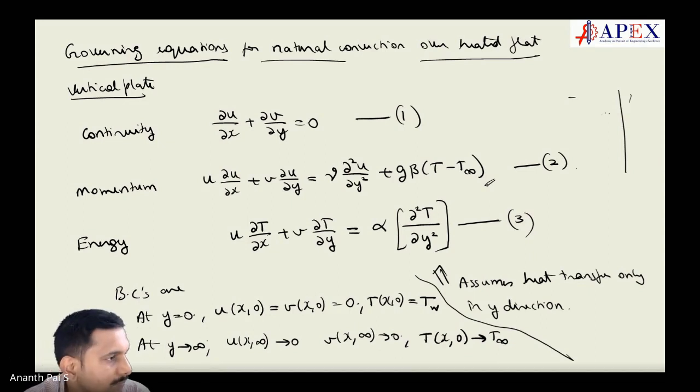pressure is not there. Since the pressure term is not there, what we generally do in CFD is first solve the energy equation. It's easiest to solve. First, only taking the diffusion part, only the heat conduction equation, we solve. Next, we say the convection conduction equation.